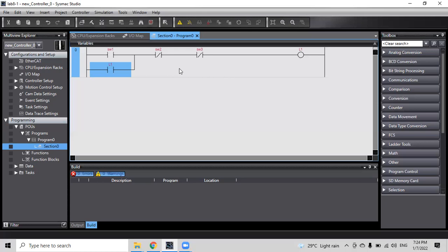It means once you trigger this one, it turns on, and at the same time this one will be closed. Once this one is closed, it's always on. So the motor on/off does not rely on SW1 anymore. This is the meaning. Unless one of switch 2 or switch 3 is triggered. That's all. Once it's off, the status of this switch is changed again. All right, so this is the first line.